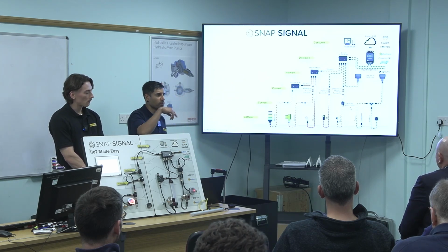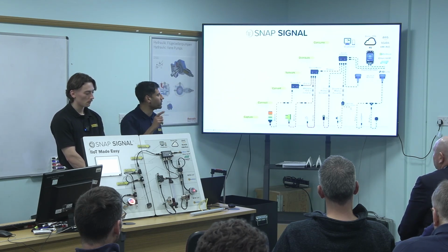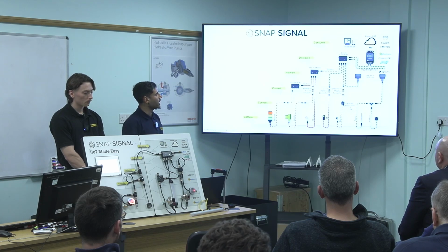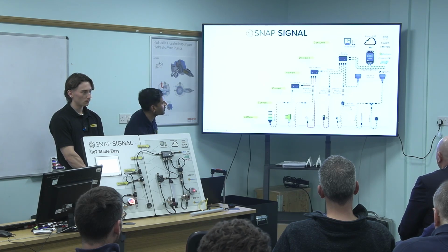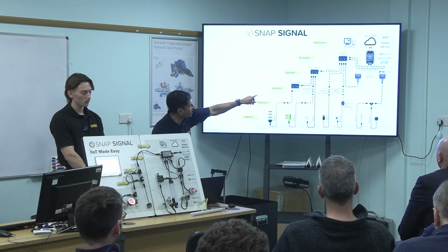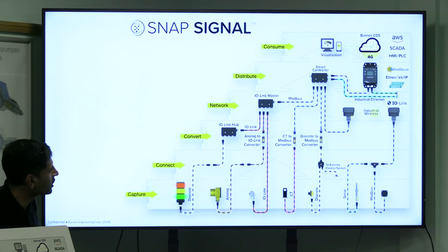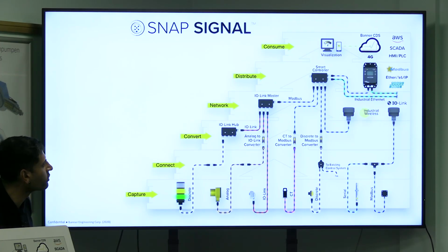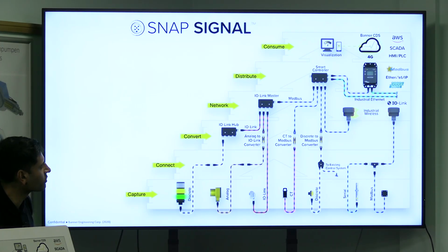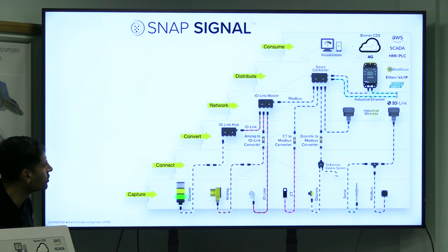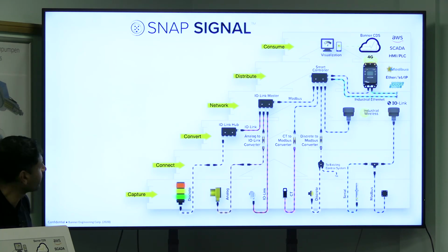And again, you can do all the manipulation, all the scaling within the controller, and then publish it to wherever you want to publish it to. It also shows our industrial radios there on the right, how we can, because it's a Modbus industrial radio, transmit the signal wirelessly if needed.